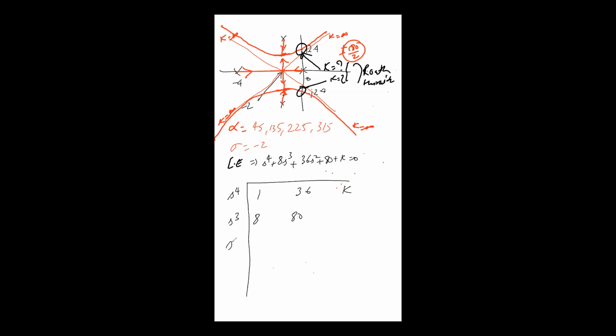Right. Fill the next row. This will be 26 equals k. This will be k. Fill the next row. This will be (2080 minus 8k) upon 26, and this will be 0. Next will be k. So to make it marginally stable, this element has to be 0. So (2080 minus 8k) upon 26 has to be 0.